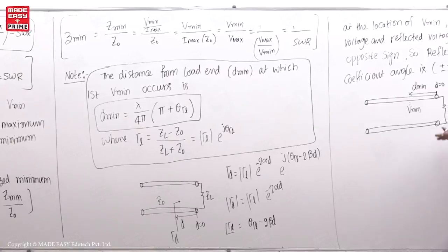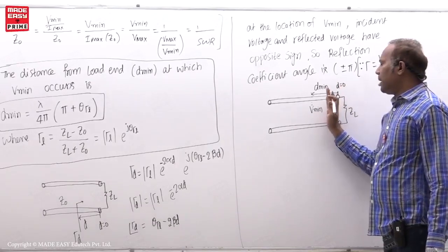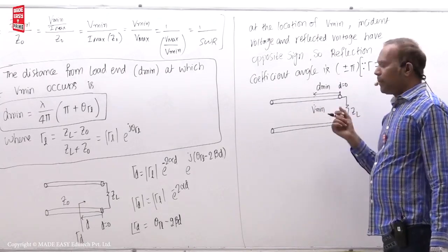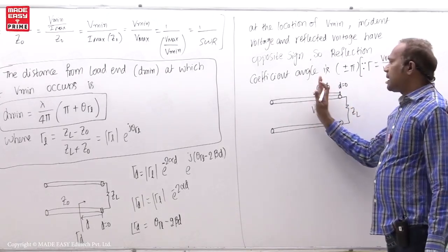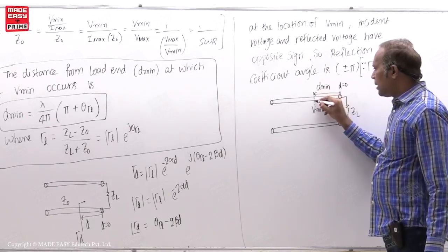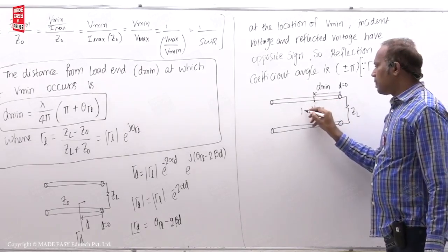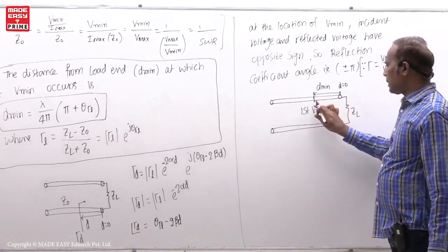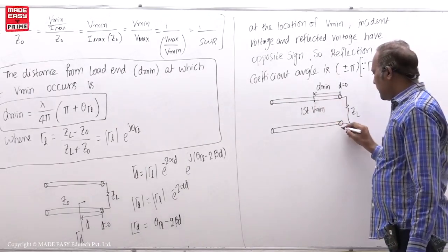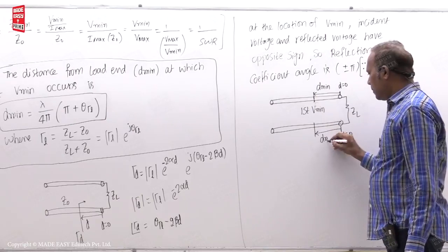So dear students, here d0, for example, you are coming like this. When you came here, you came on the transmission line for 2 meter distance. First time you found V minimum, then you are calling that distance d minimum. What is the formula of that one? Now let us derive that here at this location. First time voltage minimum you found, so this is the first V minimum. Okay. Now at the location, that means here d0, this distance is d minimum.